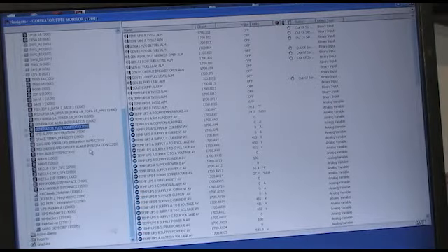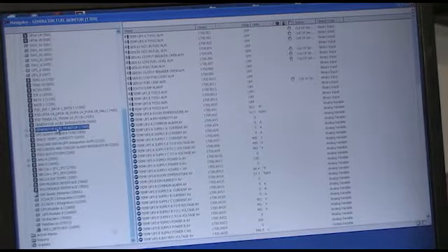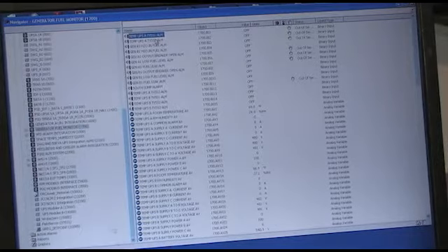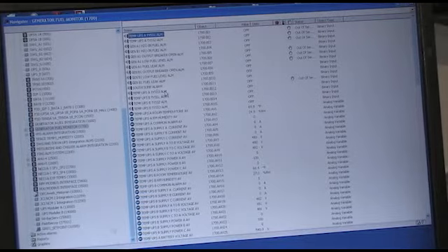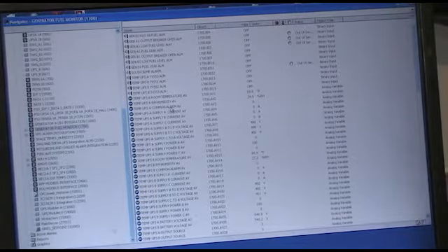All right, when logging into the system to see the temporary UPS containers, all the information that we are pulling back to the Setpoint, the Delta system, is located in the generator field monitor panel CP1700. In that panel, you will see temporary UPS A, TVSS 1 alarm, 2 alarm, and 3 alarm. That is identical for UPS B. Other points we're bringing back, such as room temperature, room humidity, a common alarm from the UPS.